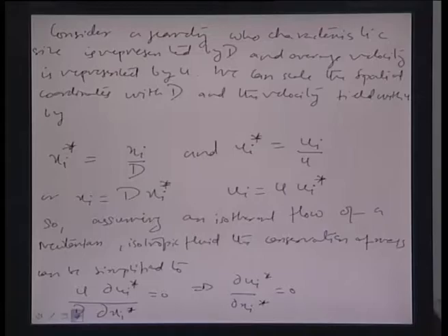So essentially let us consider a geometry. We now consider a geometry whose characteristic length is, let us suppose, d, and whose characteristic velocity is u, okay. So we represent everything in terms of d and u, time scale automatically follows suit, and as we will see the density and the pressure etc. will also be represented in terms of all these quantities, okay. So essentially that is what we will be trying to scale down, and we make these non-dimensional numbers and notate them with a subscript star, like xi star, ui star, and so on and so forth.